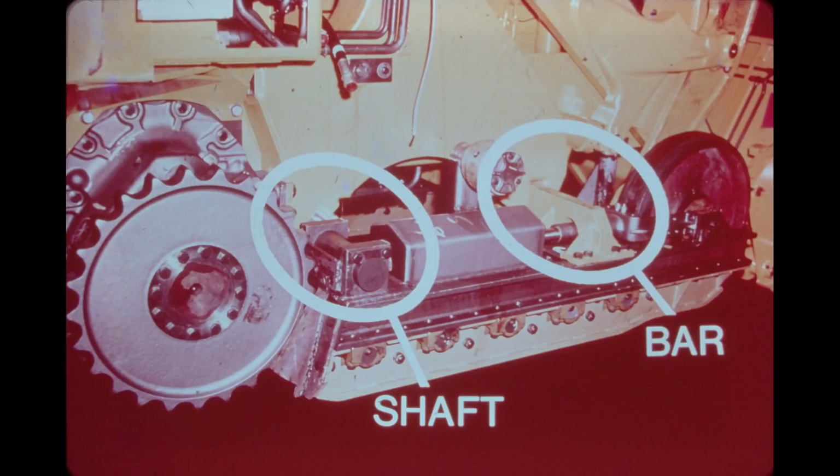The 125C and 100C loaders, as well as the small dozers, TD7C and TD8C, have rigidly mounted undercarriages, but unlike large loaders, use only one rigid bar. This bar is positioned under the front of the main frame.